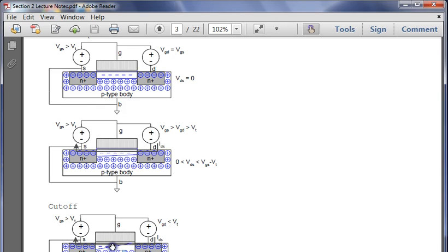If we start raising the voltage where VDS is greater than VGS, then it's going to kind of cut off the channel. So that's where our issue happens. So that's kind of a small overview.